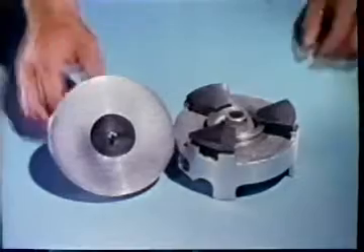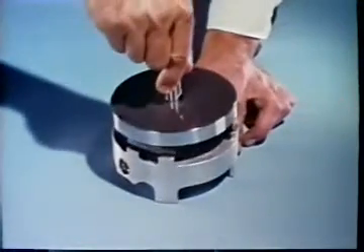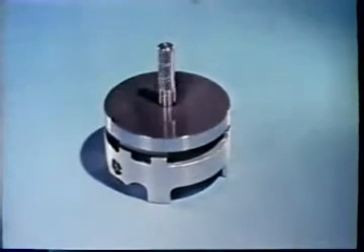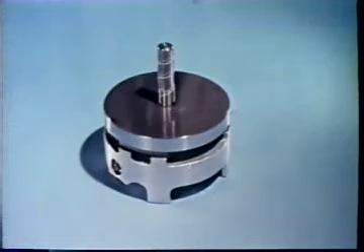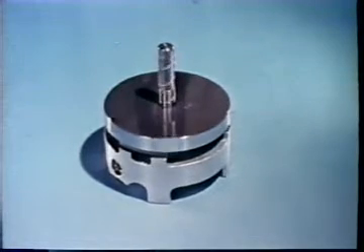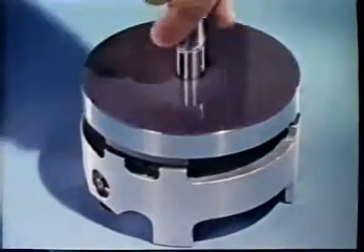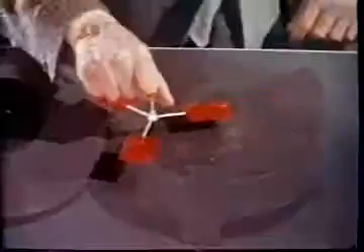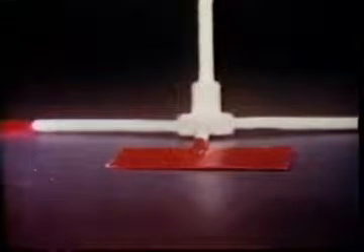To reduce the friction between continuously moving surfaces, it is necessary to introduce the lubricant at a place where the pressure is low and sweep it into a place where it is high. It was only when a method for doing this was discovered that the design of thrust blocks capable of maintaining the large load between a ship and its propeller ceased to be a major difficulty in the development of large steamers. This little device, which I call a teetotum, works on the same principle.